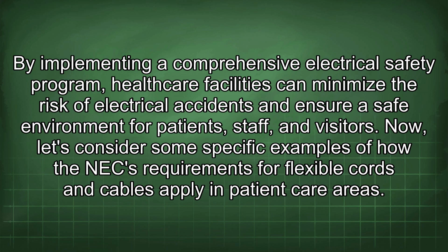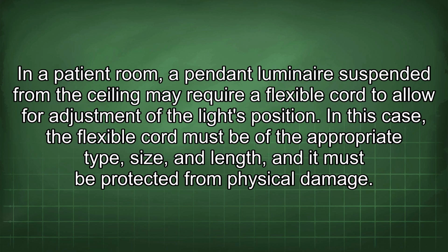Now, let's consider some specific examples of how the NEC requirements for flexible cords and cables apply in patient care areas. In a patient room, a pendant luminaire suspended from the ceiling may require a flexible cord to allow for adjustment of the light's position.